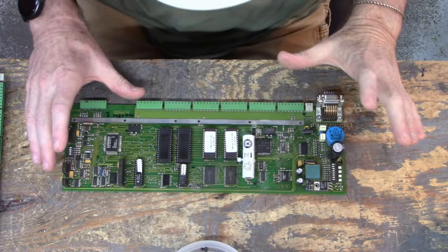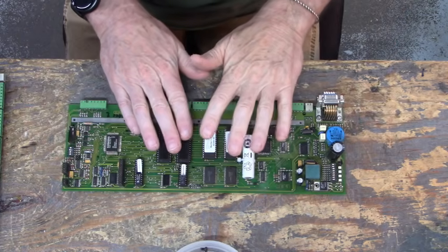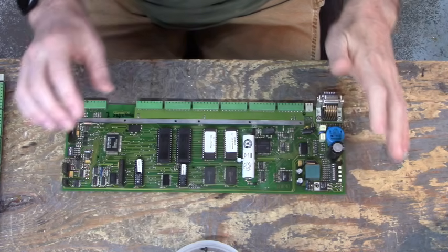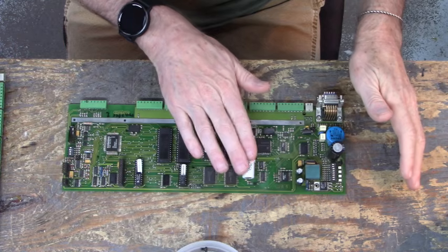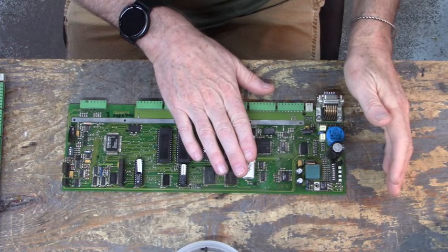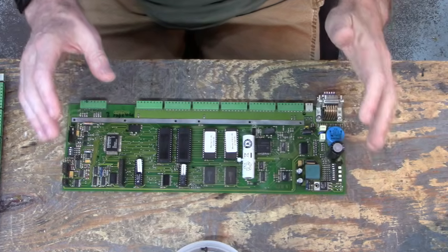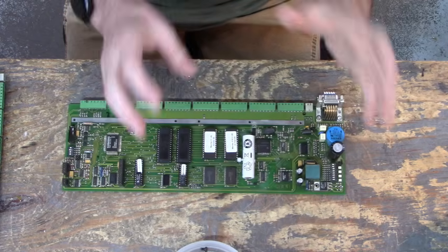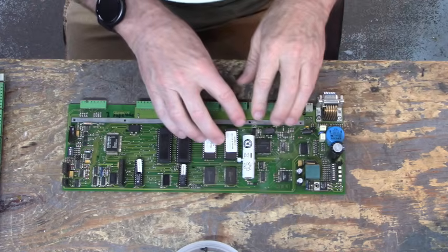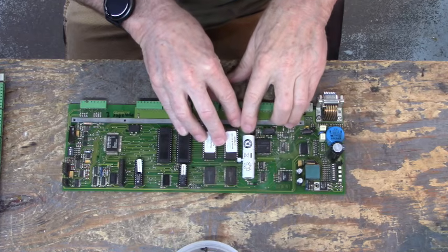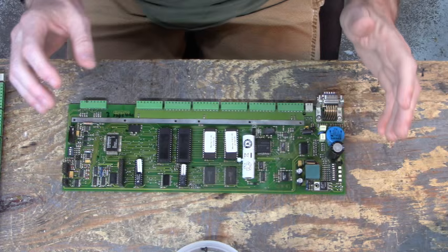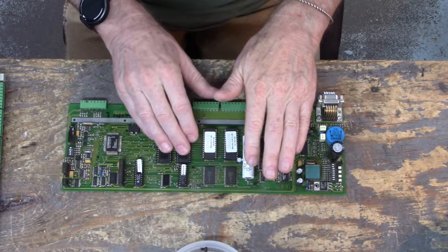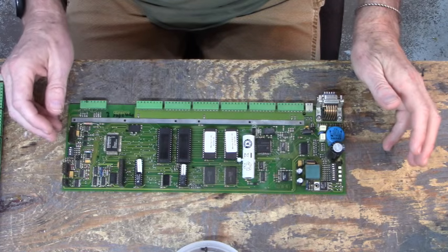All right, let's put the Kuhnke back together. This is the control board. And here's the SRAM backup battery. I don't like the way they did this. They got the battery in the very bottom of the board where you have to take the whole thing apart to change the battery. And the battery will invariably leak onto the board and eat up these traces down here. And then you have problems with your board because of open traces. Very, very bad design. Other than that, this is a fantastic system.